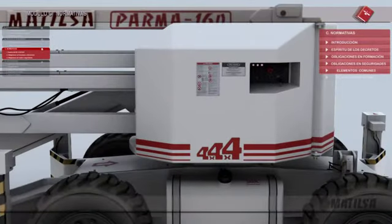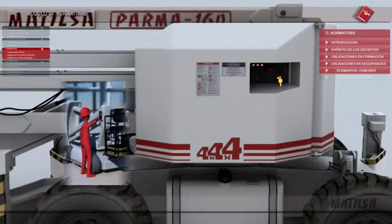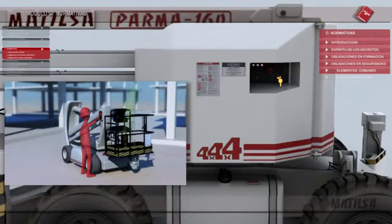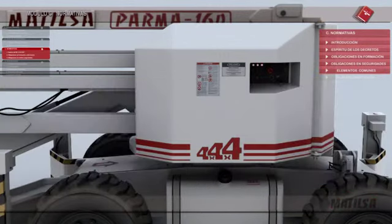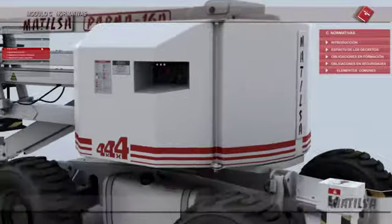Ignition key. Normally located on the board of controls at the base of the machine, it may also be found on the basket as an auxiliary feature. On batteries or electrically operated machines, these are useful, as one may choose where the machine is going to be operated from, either from the ground or from in the basket, apart from originating the contact. On diesel machines, they are useful for starting the combustion engine. Each manufacturer is free to situate it in the most convenient place.